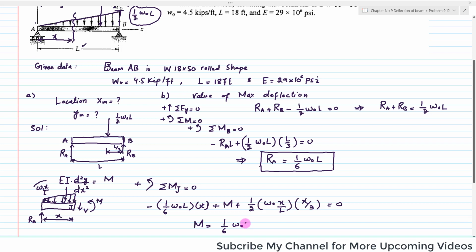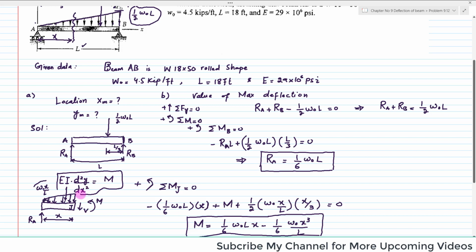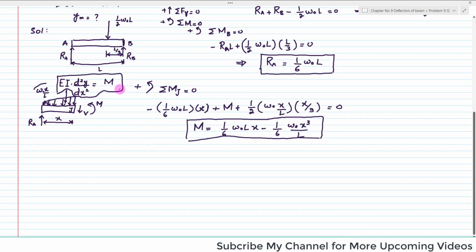So again when you simplify this, the moment comes out to be 1 over 6 W naught Lx minus 1 over 6 W naught x cube over L. So this is the moment equation which we will use in the above equation that we have written. This is the equation. Clear? So you have to put this equation in this equation.